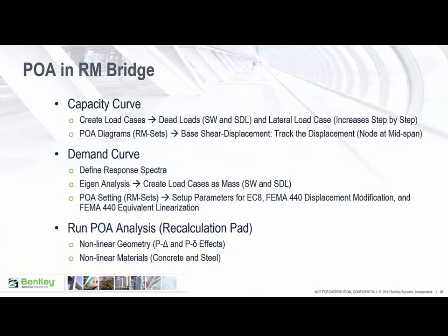Pushover analysis in RM Bridge. For capacity curve, we need to create load cases for the dead loads and a lateral load case that we increase step by step during the analysis. And also we need to define our diagrams in RM sets. The diagram is for base shear displacement, and in this diagram we track the displacement, which we consider at the mid-span.